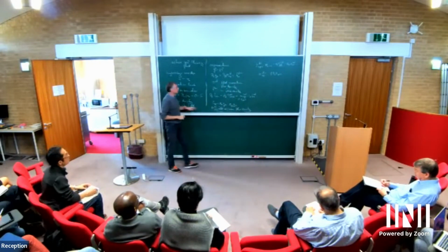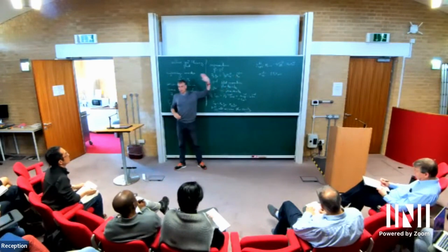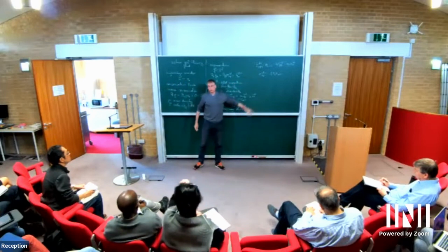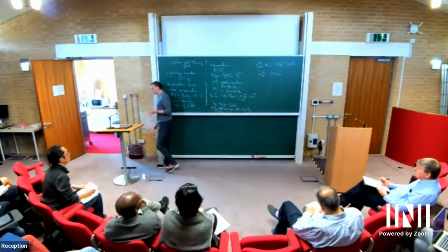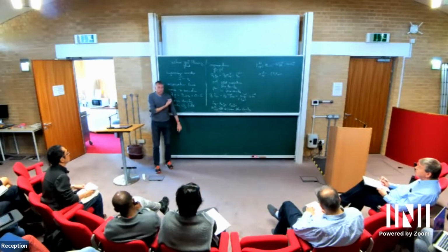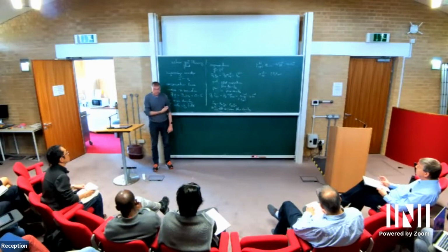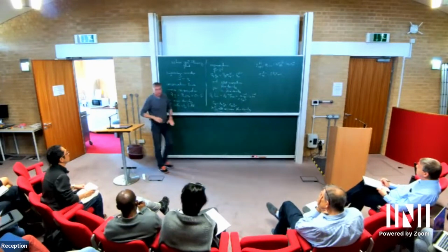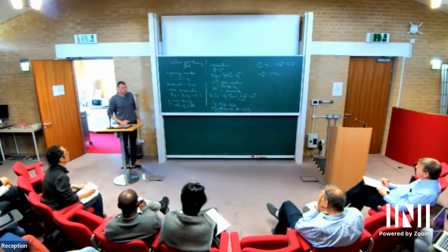So in all that I'm doing, I'm going to maintain this antisymmetric part. In principle, you could also equivalently use a different form of the stress tensor where you get rid of the antisymmetric part. It's all resolved by Martin, Parodi and Bertrand. But again, let's keep with this one. And you'll see in the end if you want to make modifications.